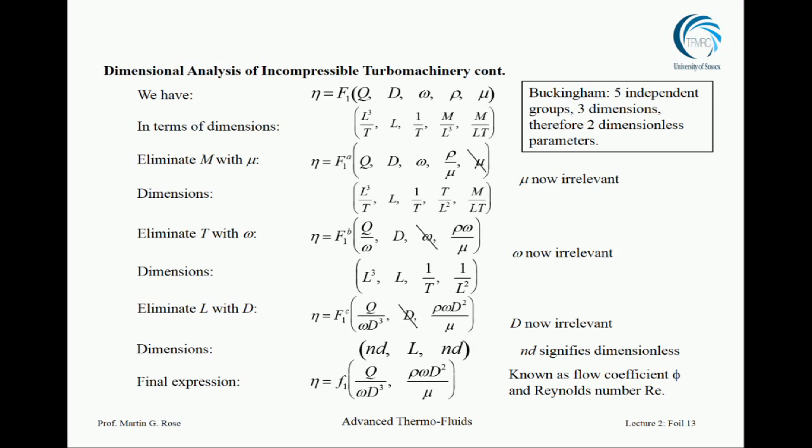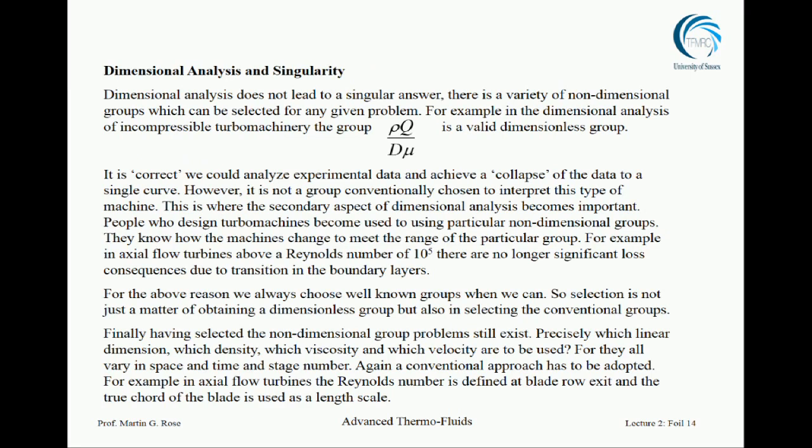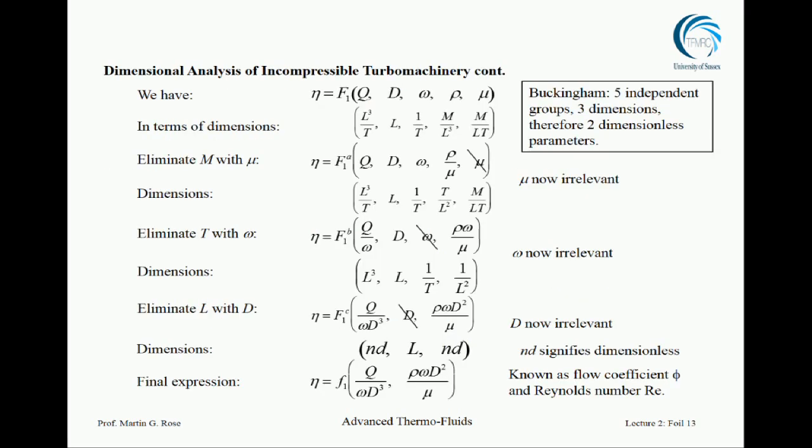So could we try to get any correct answer? For example, if we go back to the last slide, we divided rho over mu, didn't we? Yes? If we did, vice versa. Like mu over rho instead. I think from a scientific standpoint, it's completely satisfactory to do it the other way. But we will not get the Reynolds number at the end. No, you get 1 over Reynolds number as an answer because you've inverted it. But that's what the foil is about.